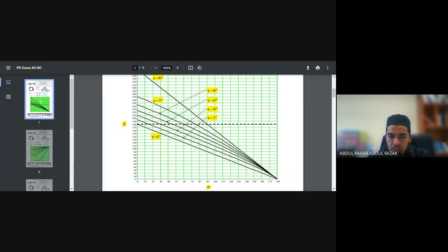If you trigger at the first point, it is 0, and the highest is 180, meaning it can only be triggered from 0 to the half cycle. This is the positive cycle. After 180, it enters the negative cycle and you cannot trigger it anymore.